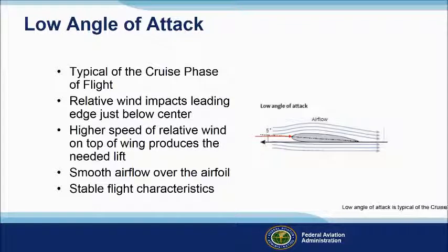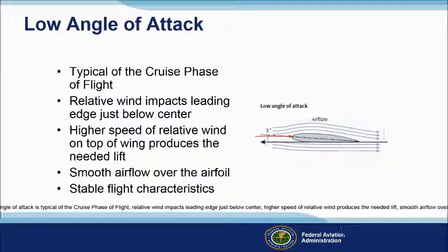Low angle of attack is typical of the cruise phase of flight. Relative wind impacts the leading edge just below center. Higher speed of relative wind produces the needed lift, smooth airflow over the airfoil, stable flight characteristics, and is responsive to control input. This AOA is typical of an airplane in cruise flight.